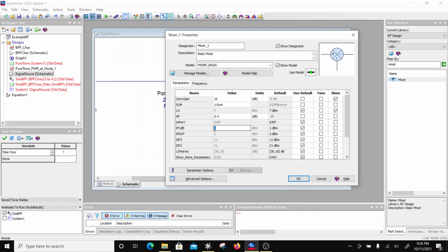Now when you specify linearity, you would say where does the gain become 9 rather than 10. You have to specify that power where the gain will drop by 1 dB. So let's say that this happens at minus 30 at the output. So you can push the input to the mixer up to minus 41, and at that point the output is going to be minus 30. So it is compressed by 1 dB.